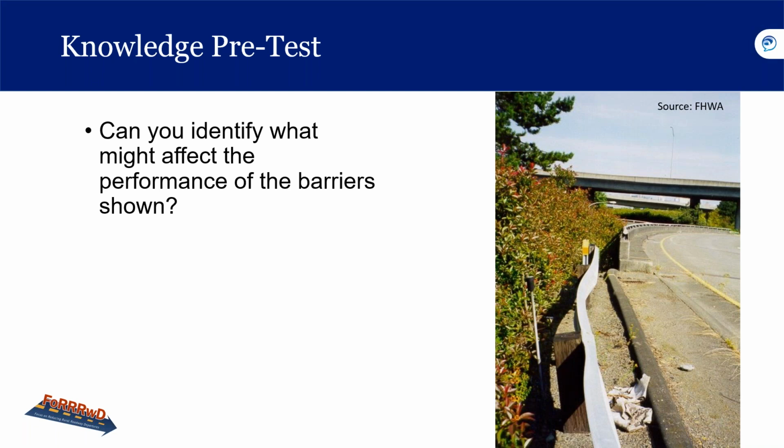So if a car comes through there, what's it going to do? What's it going to end up doing? Matt says guardrail not connected to parapet wall. Curtis says need to attach to barrier, eliminate curb. Sarah says not connected to wall, bridge, rail. Khalil says discontinuity. David says guardrail guides car to hit abutment.